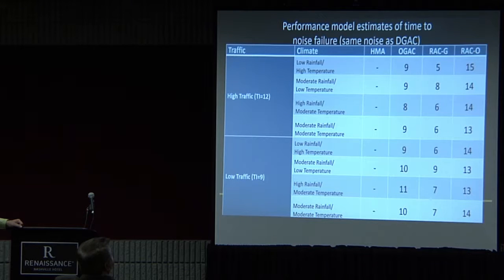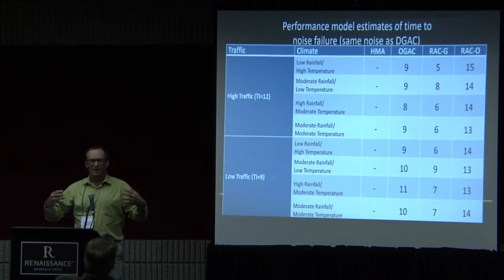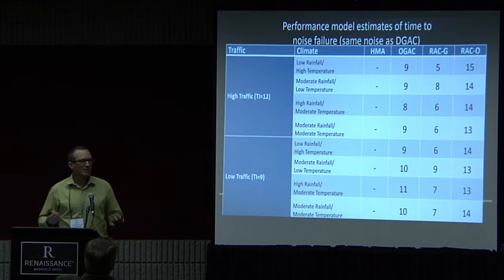Now the last couple of years of that, it's approaching whether you can perceive that, but this is a metric we're using. The rubberized gap graded, not as much. It's not actually originally intended. There was a lot of talk early about rubber being an absorbent material and having a high impedance, and we did impedance tests all over the place, and it's not really absorbing that much noise. It's really about noise generation. Pavements don't absorb that much noise from what we can tell.